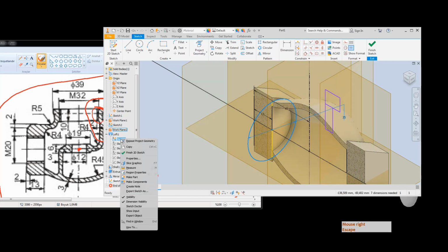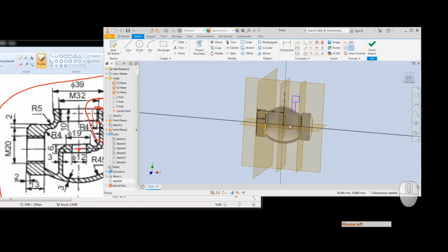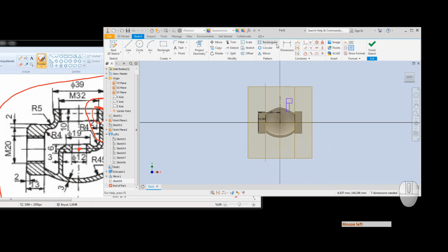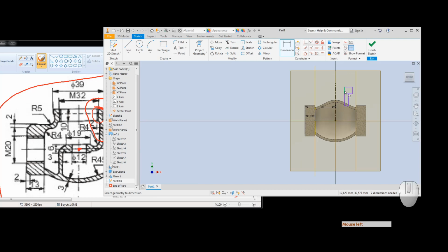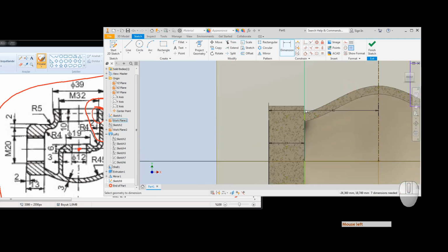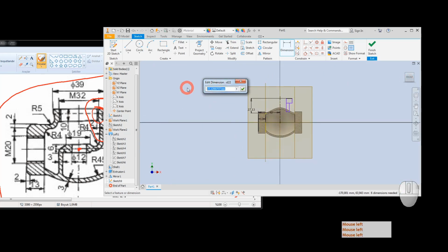We create a dimensional relationship between the first sketch and the total height of our part by just getting a relationship between the circle here and the top side. And we give that dimension by using a projection line from the circle which we have created. The dimension relationship to the top side is 10 plus 4.